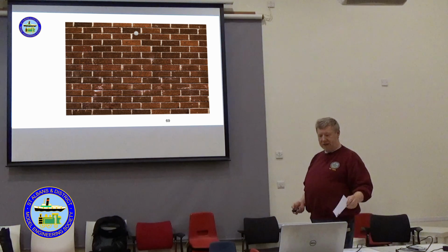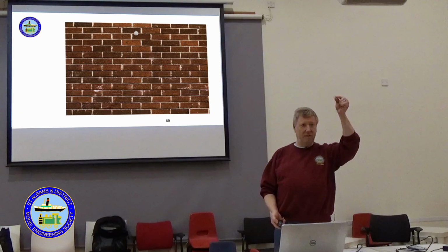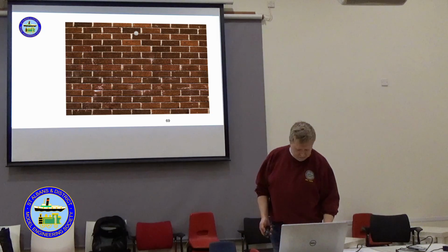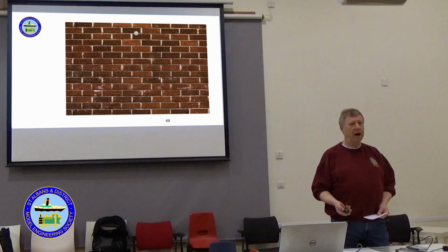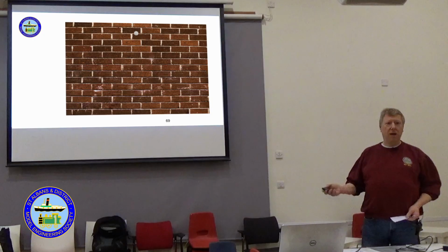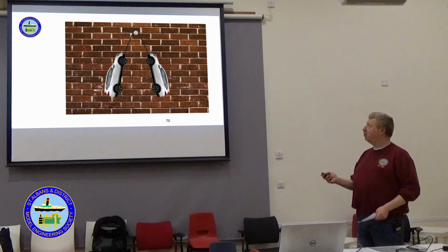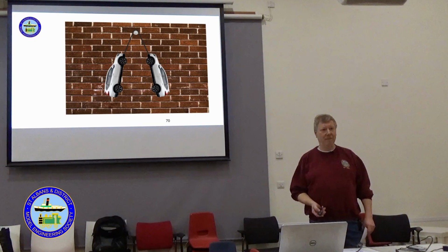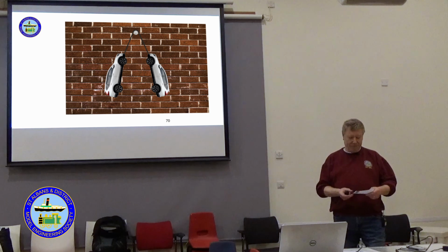And as I said earlier, the typical contact patch is a 50p piece. I want you to visualise how much friction we're talking about between a locomotive wheel and a rail. If I were to stick a 50p piece to a wall and then suspend two family cars from it, that's how much friction is needed at a wheel-rail interface. That is a hell of a lot of friction in there.